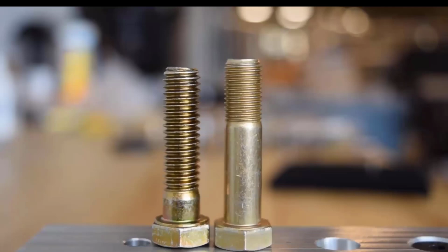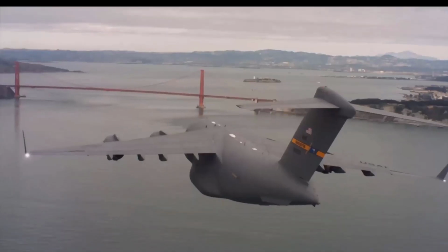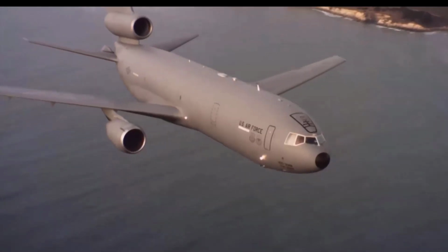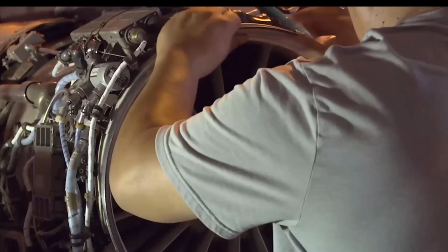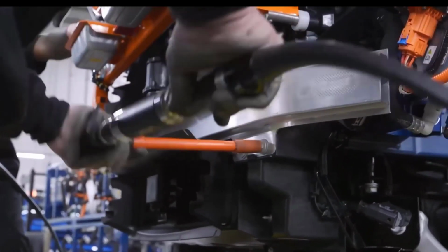Fasteners are available in both coarse and fine threads. Coarse thread fasteners, conforming to the UNC thread specification, have fewer threads per inch and are generally the first choice. However, fine thread fasteners are used in high-performance applications like aerospace and automotive because they have several advantages. Size for size, fine thread bolts are about 10% stronger than coarse thread bolts, and the lower helix angle makes them more resistant to vibration. However, they are easier to cross-thread and don't tolerate debris or thread damage very well.